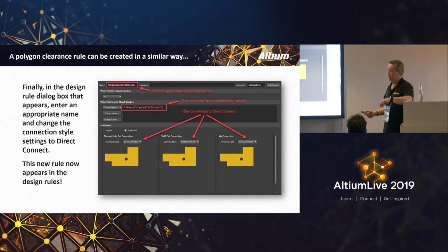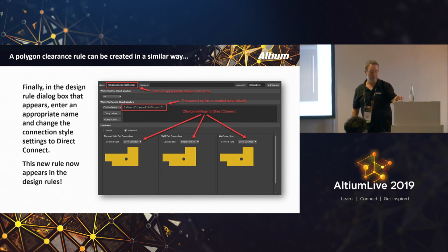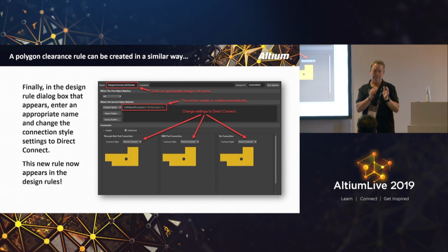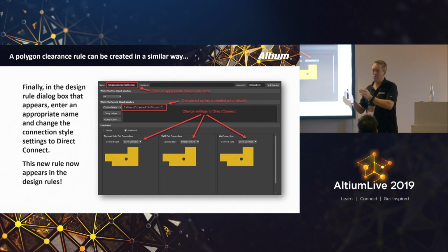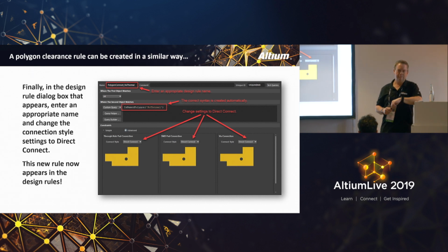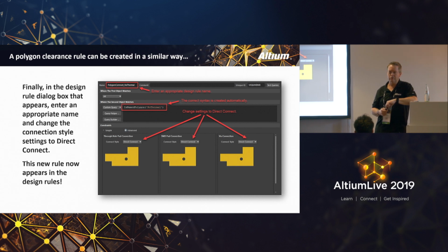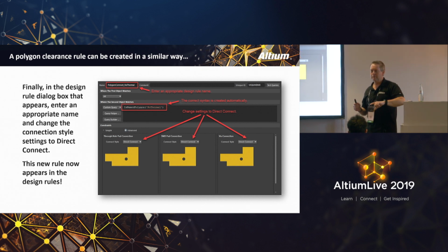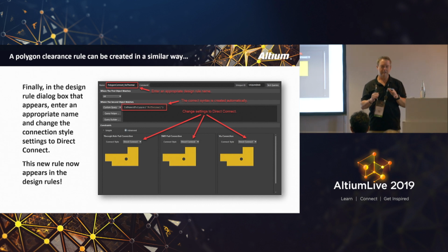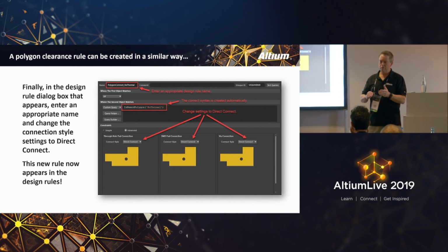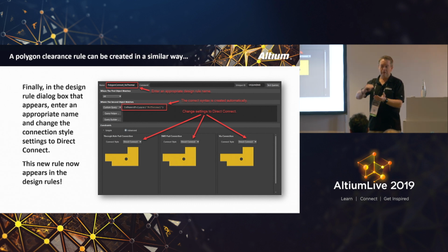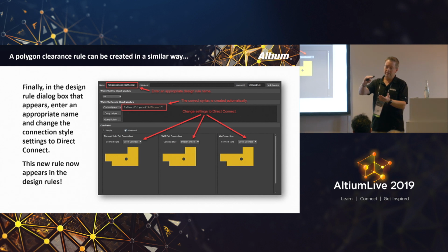Works out very nice. Now, some of you may be thinking, well, why don't you create a rule that says thermal and not no thermal? Well, I did try that the first go around, but what I learned from that and what I want you to understand is you want your default rule in any of your categories to just kind of be the catch-all. So if it doesn't meet this criteria and this design rule, it goes to the next, down the hierarchy or the priority list.